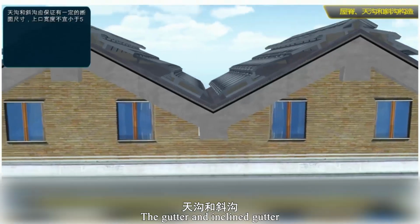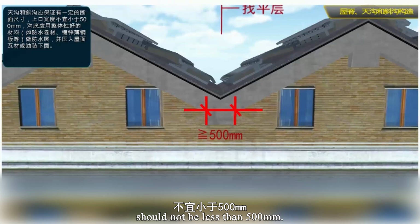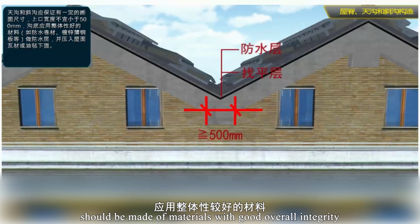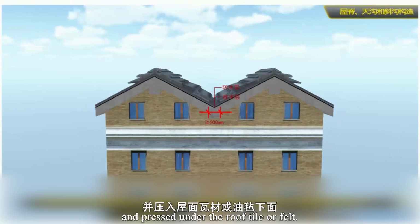The gutter and inclined gutter should ensure a certain cross-sectional size, and the width of the upper opening should not be less than 500 millimeters. The bottom of the gutter should be made of materials with good overall integrity, such as waterproof rolls, galvanized steel sheets, and so on, as a waterproof layer, and pressed under the roof tile or felt.